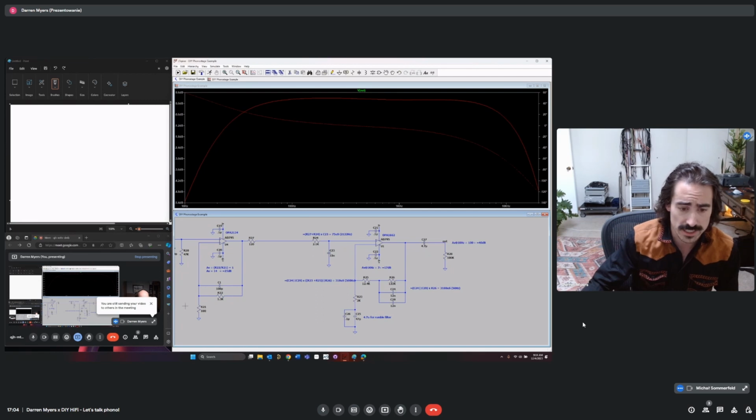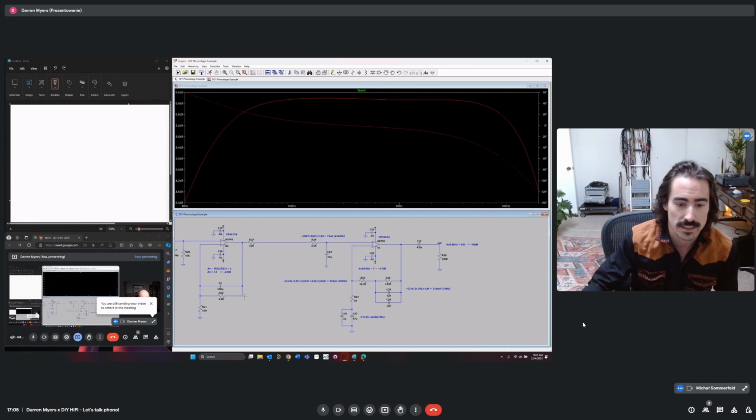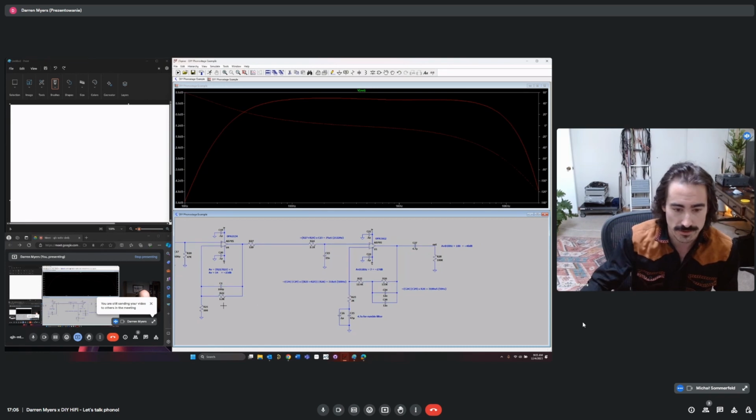And that's what you see on these phono stages: roughly in the first stage, you're looking at 100 ohms for that value, and it doesn't seem to be dominant, or I should say it's not dominant. The amplifier at that point is the dominant noise source, and that's exactly what you want. You don't ever want a case where this noise becomes larger than the noise created on the input of the amp. That just means that your network is going to be too large in value.